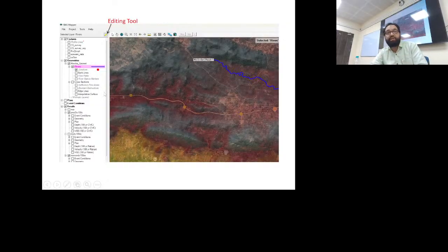Then we can draw the river reach. In 1D, we were directly drawing the river reach without any background. In 1D also there is an option, but here it is much easier. If we have terrain data and web image all laid together, then 2D is simpler than 1D. Once we have this, if we click on geometric data, then we have to select River.